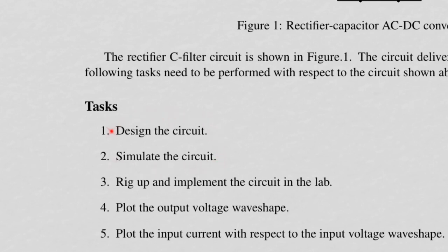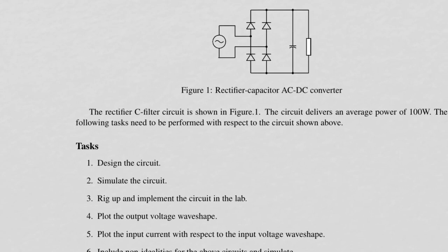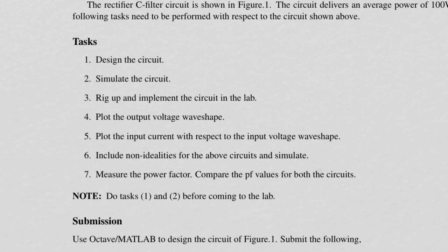After you have understood the circuit, you can introduce non-idealities, such as track inductance and resistance, and see the effects of all these non-idealities on the operation of the circuit and the waveforms at various points. After you have become conversant with the circuit, you can then begin the other portions of the tasks.